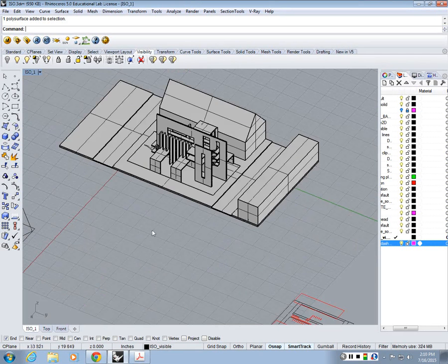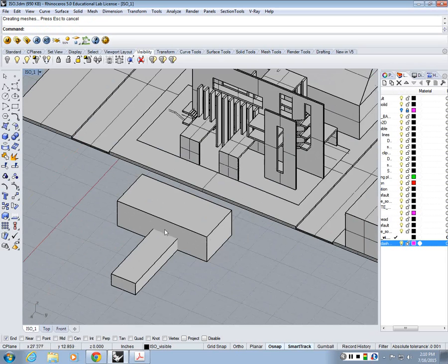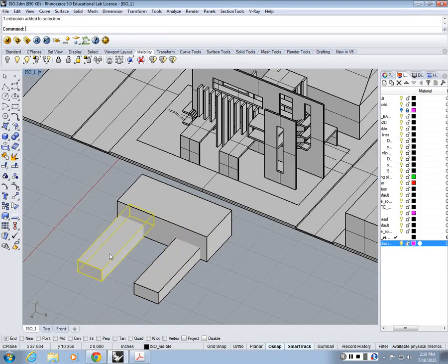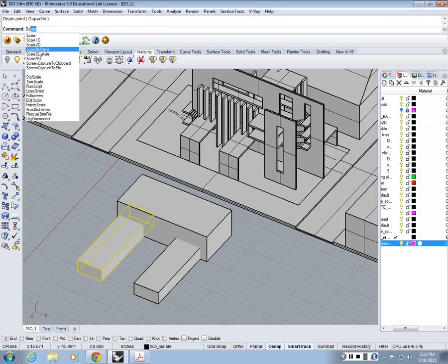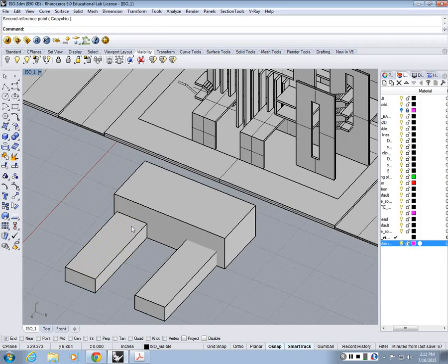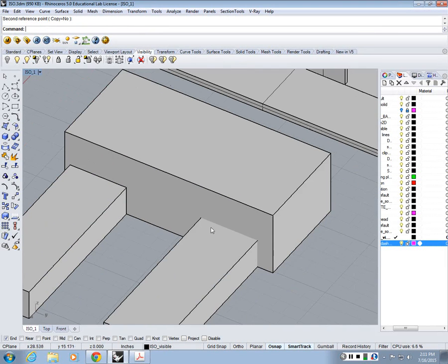One thing that is worth mentioning. Let's say I have 2 things intersecting like this. When you're doing solid modeling, let's say this is the situation you have. I'm going to make another one and just show you what the difference is when you do make 2D. So let's say this guy is modeled correctly, so this face doesn't intersect with the other one, it's actually stopping on this face. Whatever you see in the display is what you will get in make 2D, right? So this edge I will see when I do make 2D, but here I wouldn't, because 2 solids are intersecting, they're not sharing an edge.